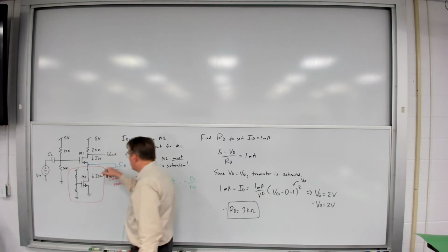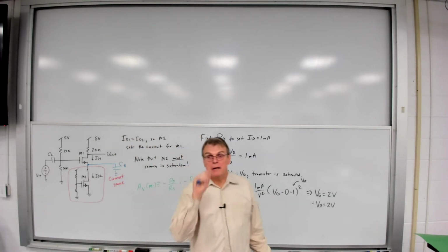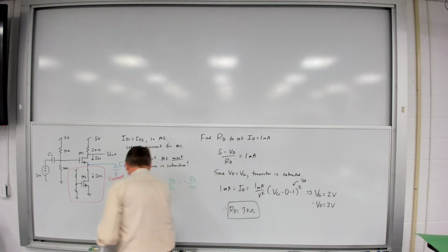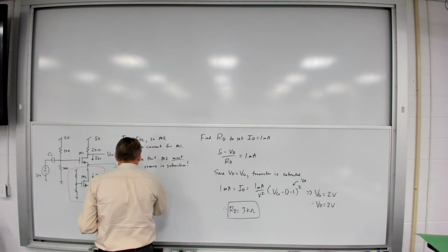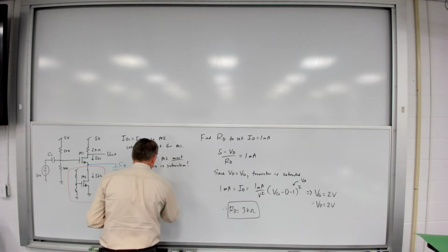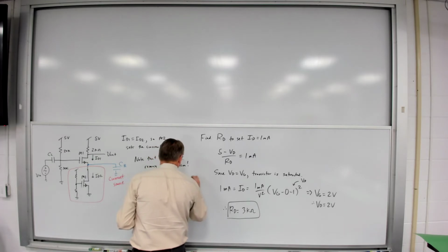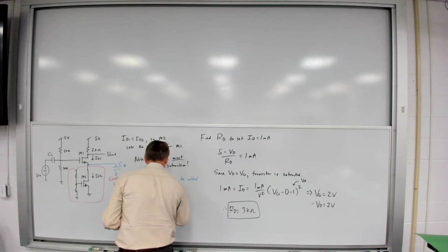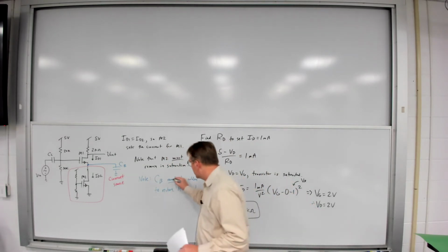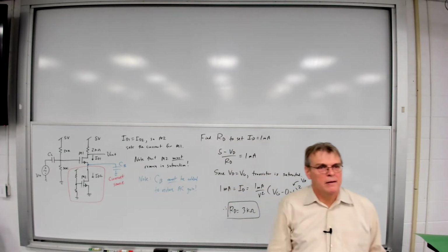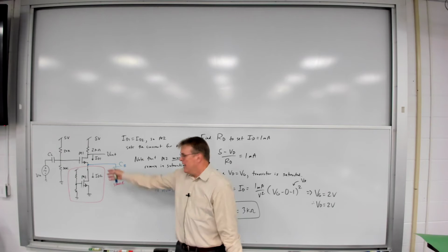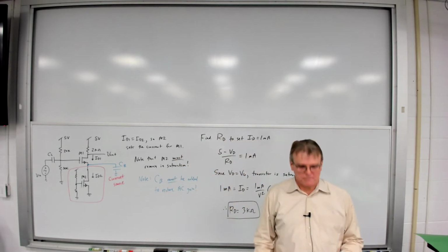So DC-wise, the capacitor has no effect on the biasing, because that's all DC. But in the small signal, in AC, now that source is grounded. And now you get a working amplifier again. So we note C sub B must be added to the circuit. So if I want to restore my AC gain using current source biasing, then I've got to have a bypass capacitor. Well, no surprise here, when we had a source resistor there, we bypassed it, right? Same thing here, except now I'm using a DC current source, but still I'm bypassing it.